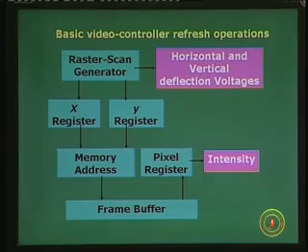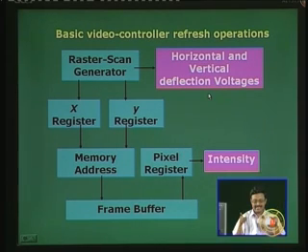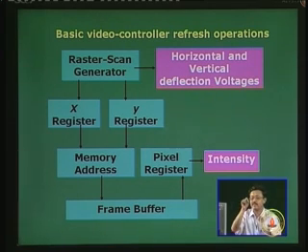So, you must know what should be the intensity or the color of that point, and hence the strength of the beam must be controlled to give it the desired intensity at that particular point. So, if you look back into the figure, essentially the video controller must give two outputs. First one, if you see within the pink shaded diagram here with white characters, horizontal and vertical deflection voltages, that dictates where the electron beam currently is and what pixel on the screen it is trying to access.